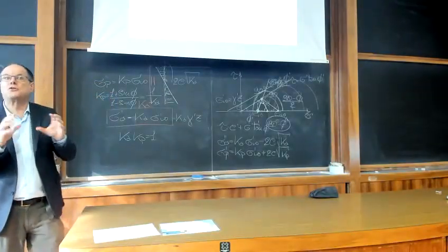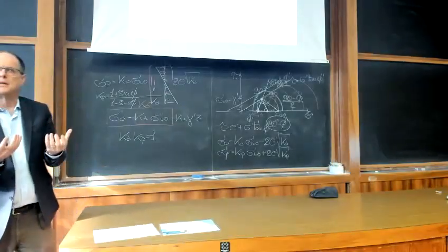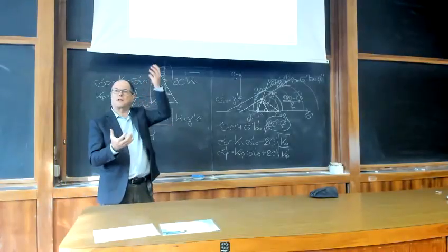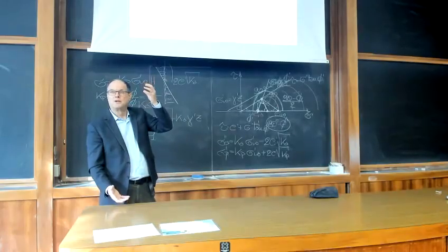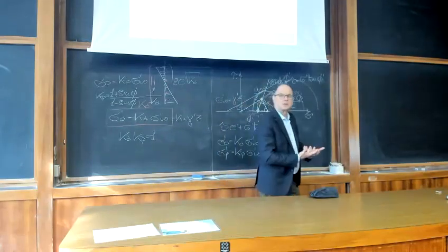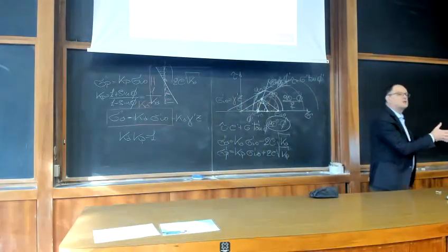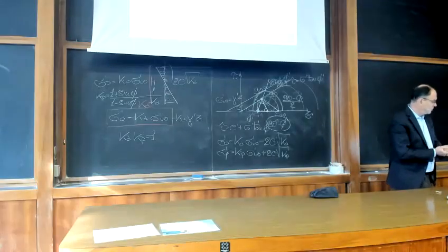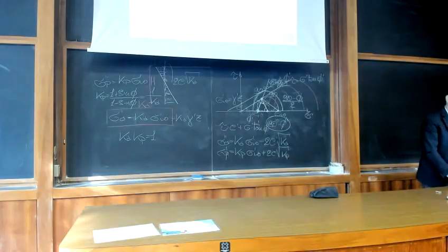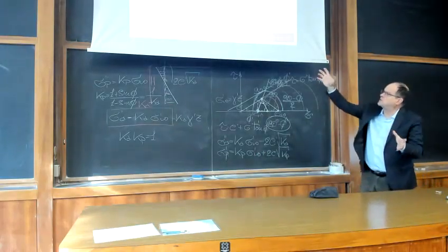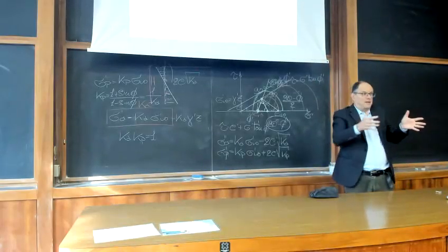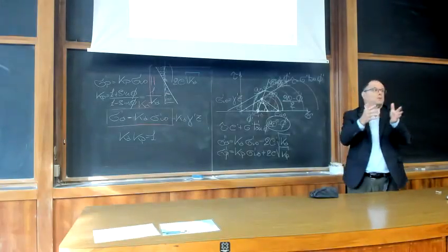But remember, the foundation is not just a structural element. The actions, the stresses on the foundation depend on the structure above and on the soil below. So as an engineer, you have to consider the soil as an engineering material in relation to this connecting element. So the foundation is the part of a structure which transmits loads directly to the underlying soil. Now, typically, the foundation, if it is shallow, just below the ground surface, is larger than the wall or the pillar, the column of your structure.